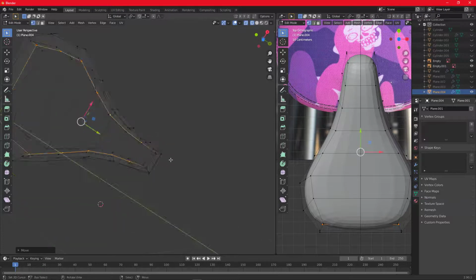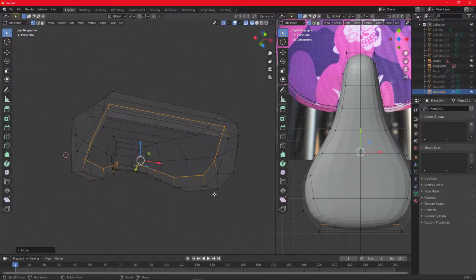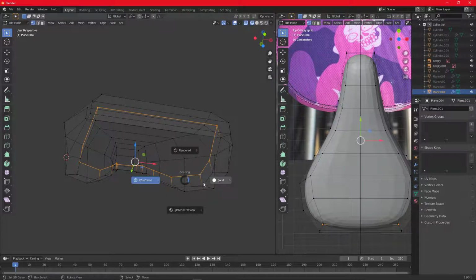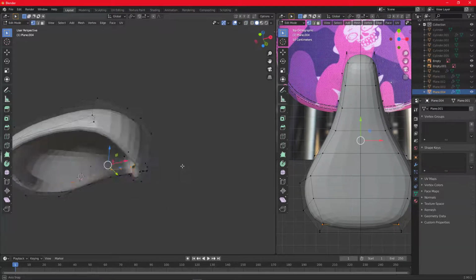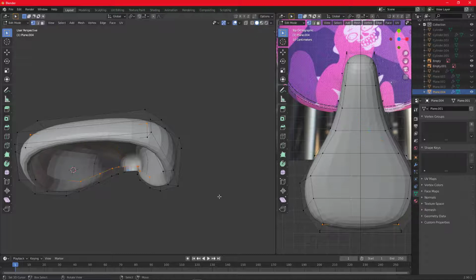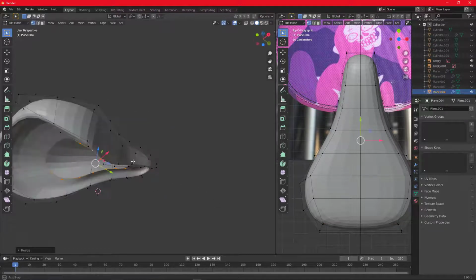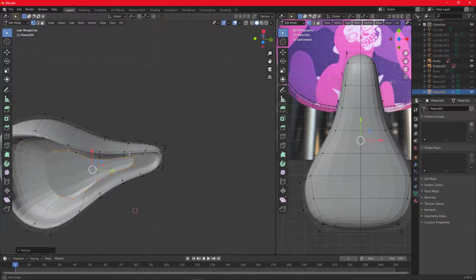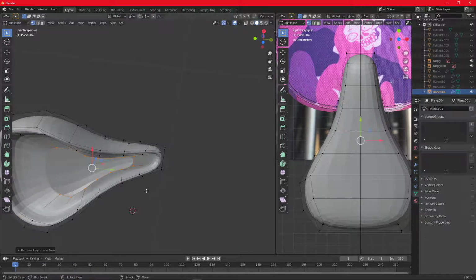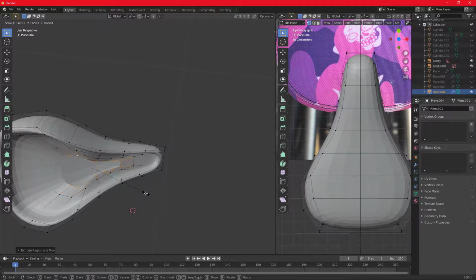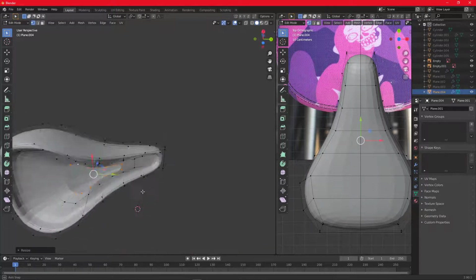Yep. So now select everything and press E, then press X, skeleton, then E and S again, skeleton, then you press F to clean face.